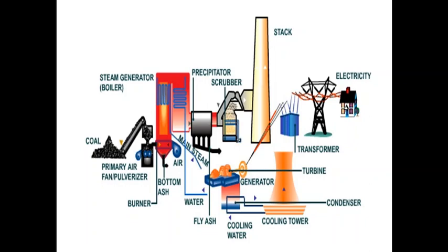It has to be prepared, it has to be fired in the furnace, and after firing we have to see that adequate combustion is taking place, and post combustion whatever heat is released is trapped appropriately in various locations of the steam generator, which is nothing but a kind of heat exchanger with heat traps.